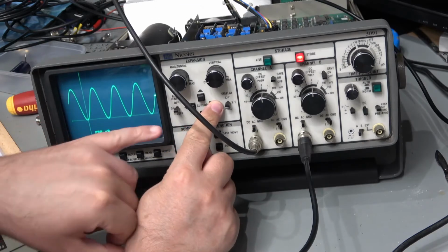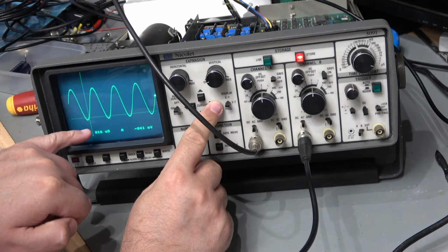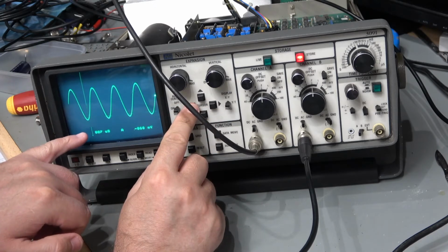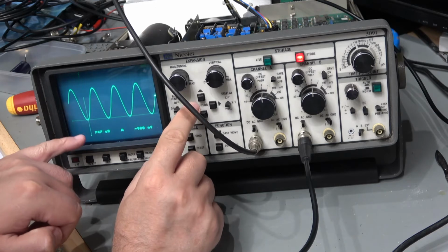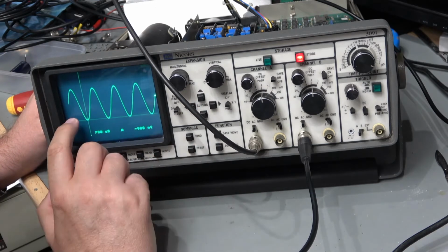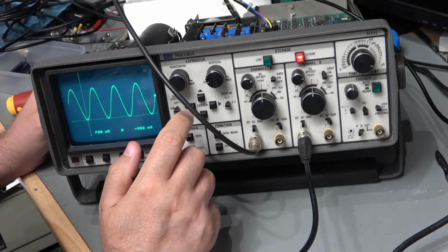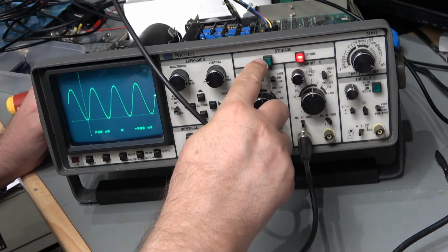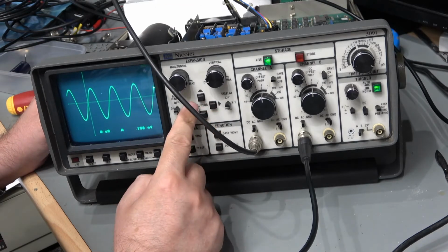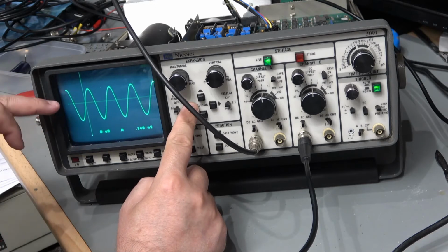And what happens now, if I turn auto center on, then as I sweep the time, the horizontal cursor lines up. Superb. So that's working perfectly as far as I can see. My storage worked, my live worked. Switch back to live. Yeah, and actually the cursor is now moving the signal relative to the trigger point.